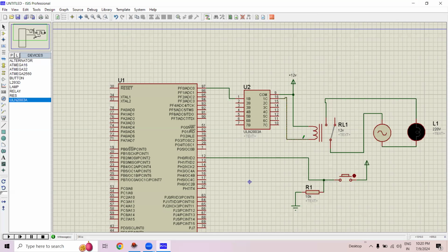That depends on whether 1C gets 0. And 1C gets 0 if 1B gets 1. And 1B gets 1 if you trigger or turn on the button or the sensor. So let's turn on and we can see the relay is triggered. Let's turn off. Again, the relay is triggered and it's off and the lamp is off.